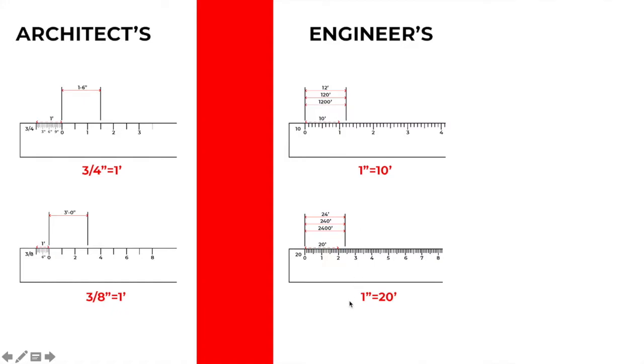Similarly, on the 1 inch equals 20 feet scale, we can add zeros to it to actually read drawings or plans that are 1 inch equals 200 or even 1 inch equals 2,000 feet if you're looking at the whole region of the Earth.